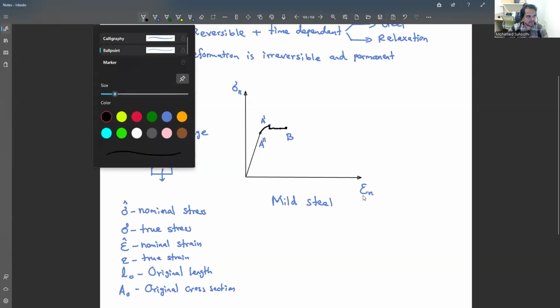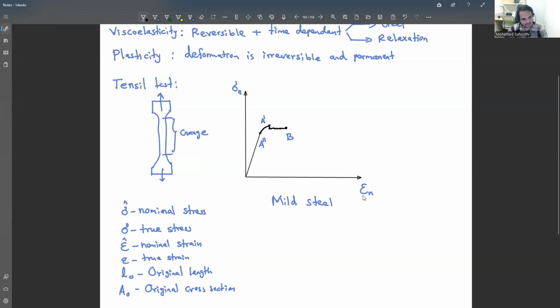After reaching this point, the material follows a nonlinear variation like this. It will go to the ultimate point, then it reaches the decline region, because of the necking. When the necking takes place, the stress will decline. Let me mark one point here, U. U will be the maximum point, the ultimate point.